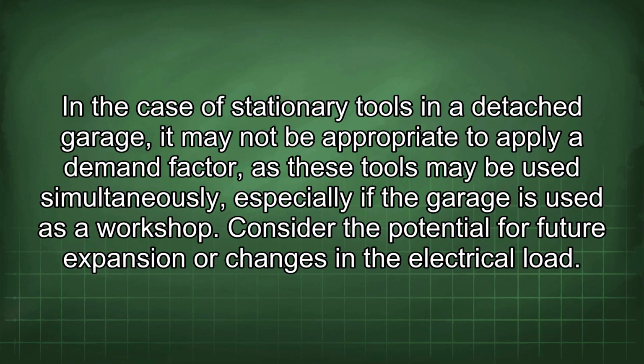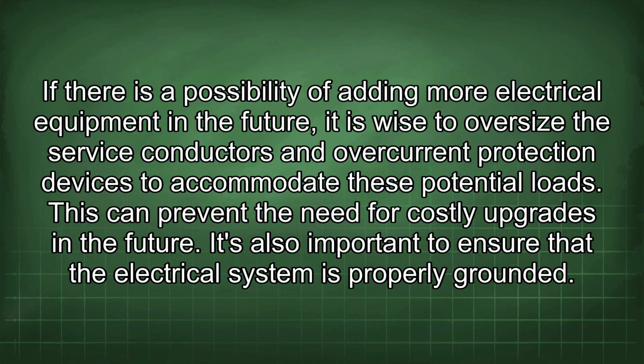Consider the potential for future expansion or changes in the electrical load. If there is a possibility of adding more electrical equipment in the future, it is wise to oversize the service conductors and overcurrent protection devices to accommodate these potential loads. This can prevent the need for costly upgrades in the future.